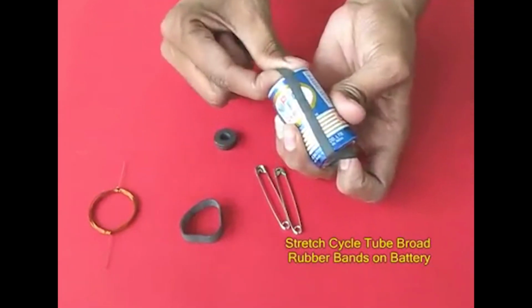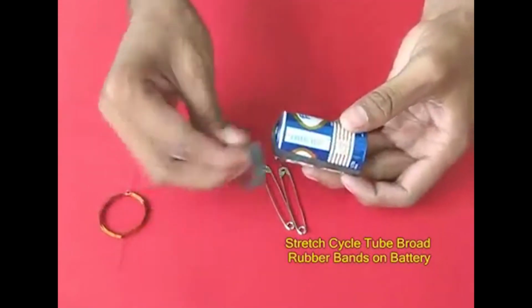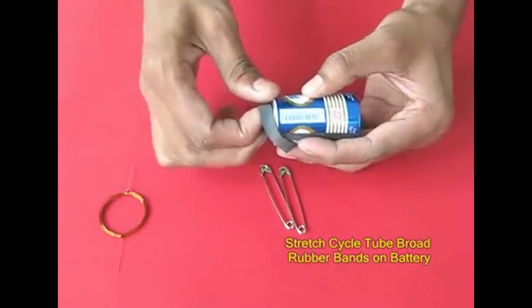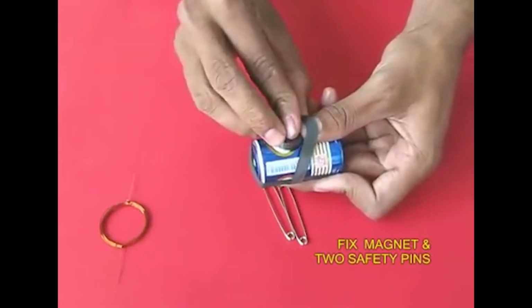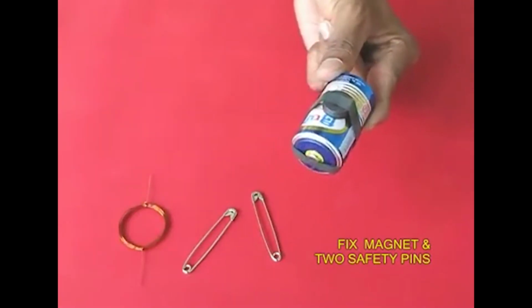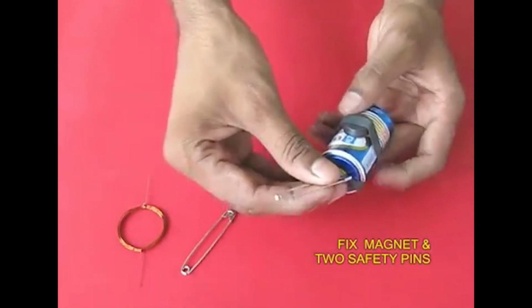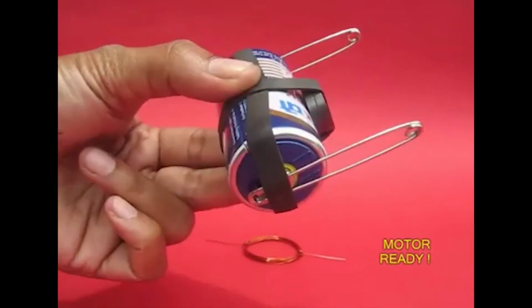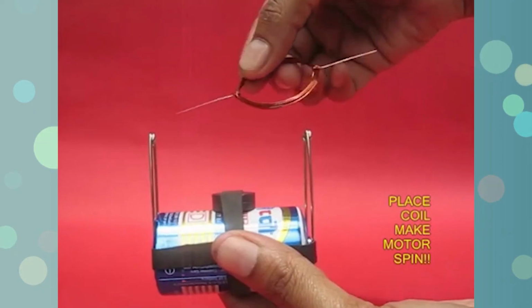Now take 1 centimeter broad rubber bands cut from an old bicycle tube, and stretch them on the battery, one across and one along its cylinder. Place a ferrite magnet in one of the rubber bands. Take 2 safety pins and fix them on the 2 ends so that they clutch to the plus and the minus of the battery. The motor is ready now.